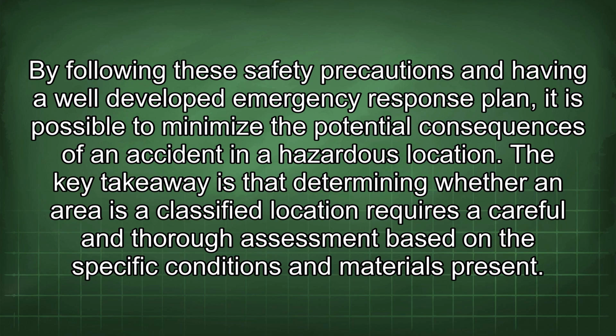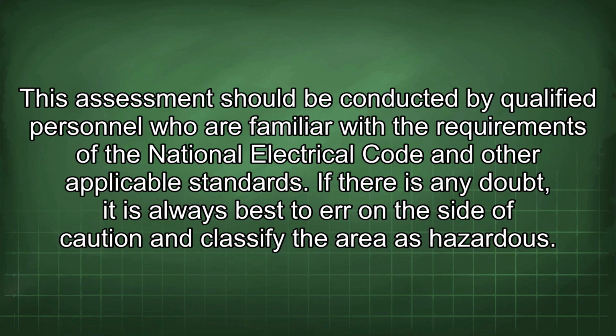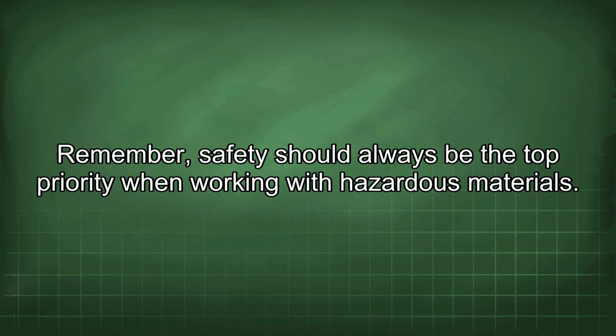The key takeaway is that determining whether an area is a classified location requires a careful and thorough assessment based on the specific conditions and materials present. This assessment should be conducted by qualified personnel who are familiar with the requirements of the National Electrical Code and other applicable standards. If there is any doubt, it is always best to err on the side of caution and classify the area as hazardous. Remember, safety should always be the top priority when working with hazardous materials.